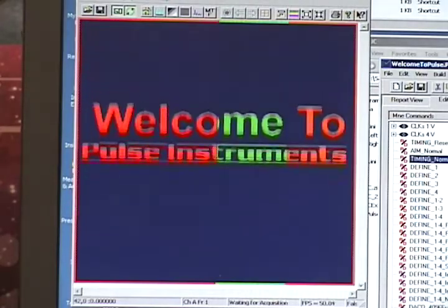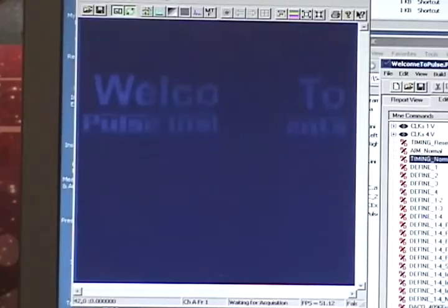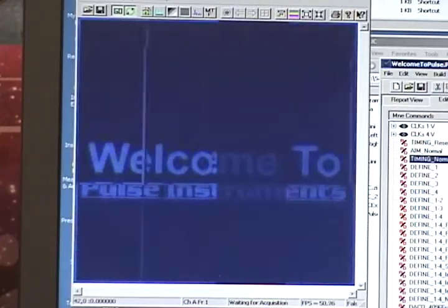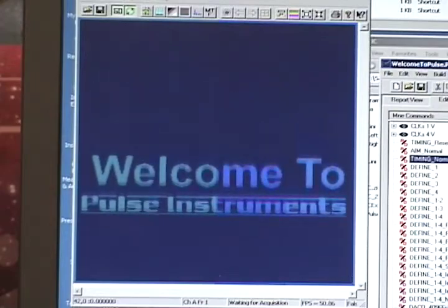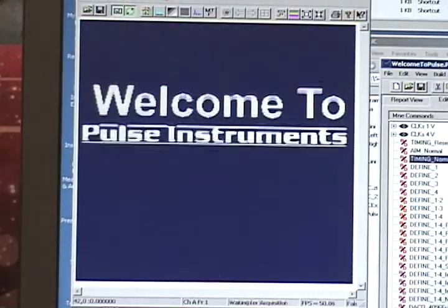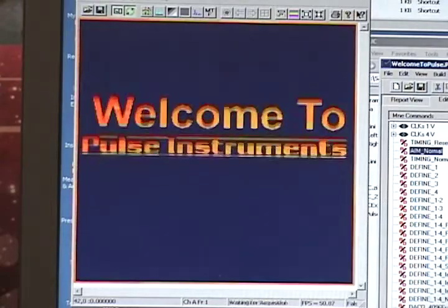Here, looking at the video signal, we see the results of the same operations. First, moving the conversion point in and out of the information well, and then moving the DC offset into and out of saturation. We also have gain in the system, from 1x to 420x, to maximize use of the A to D's dynamic range, and also to detect very small signals.